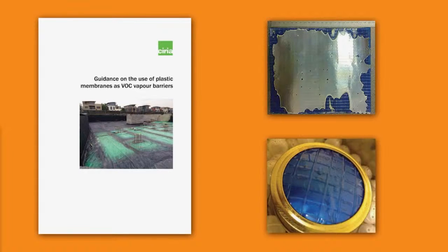Foil membranes are often considered to be a perfect solution as they offer high resistance to all types of vapour, but it must also be taken into consideration that the foil responsible for this resistance can degrade or break down over time. It's not uncommon for a membrane to pass the vapour permeation test, then subsequently fail due to degradation associated with oxidation, where vapour has permeated through the cut edges of the membrane. As part of an appropriate overall design, a membrane of lower resistance to a liquid contaminant may still be suitable provided exposure to that liquid form is minimised, for example by means of source remediation or by ensuring the barrier is located in the structure such that contact is impossible.